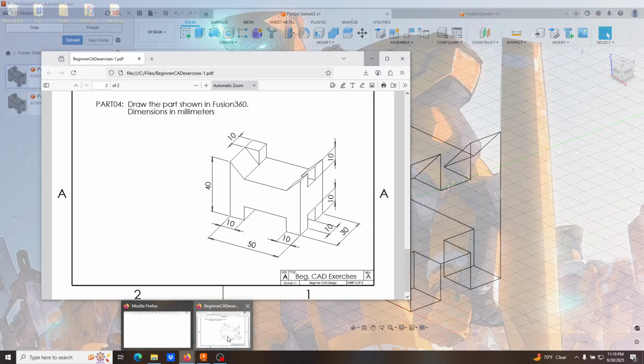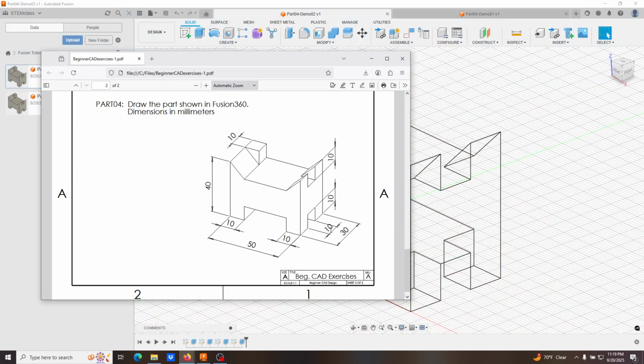So if we take this back to the image here, the fact that I have this 10 gap dimension here, I wouldn't assume that it would cut through all the way, although some people might think about it that way. And generally the idea is that if there was something different than what would be assumed, then I'd have to indicate that. Now, that's a very, very general way to kind of look at this stuff. And if you actually talk about proper drafting principles, it gets a little different. But just wanted to go ahead and mention that.